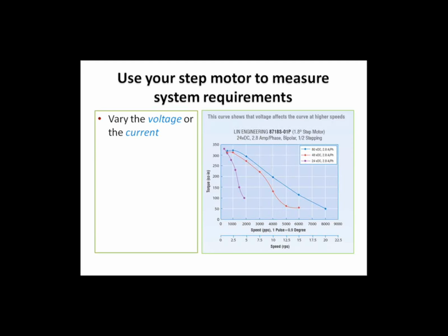And if you take that information, the speed and the voltage that you changed, or current, whichever it is, only change one of them, and feed that back to your step motor manufacturer, the step motor supplier will be able to back calculate what the torque required is.